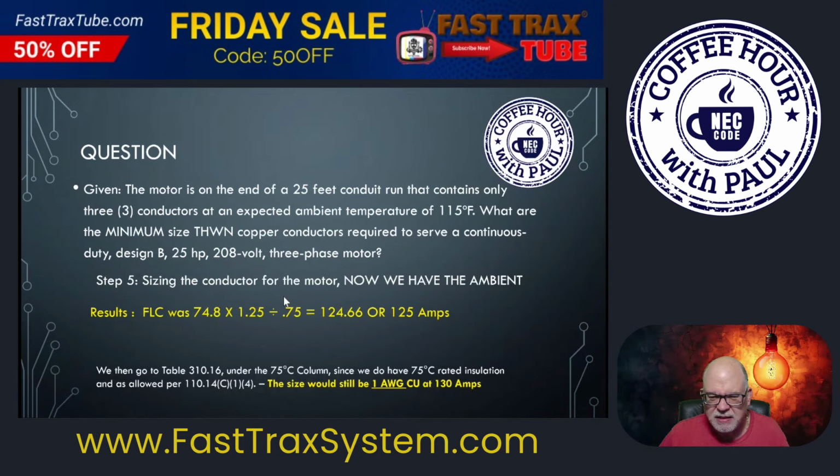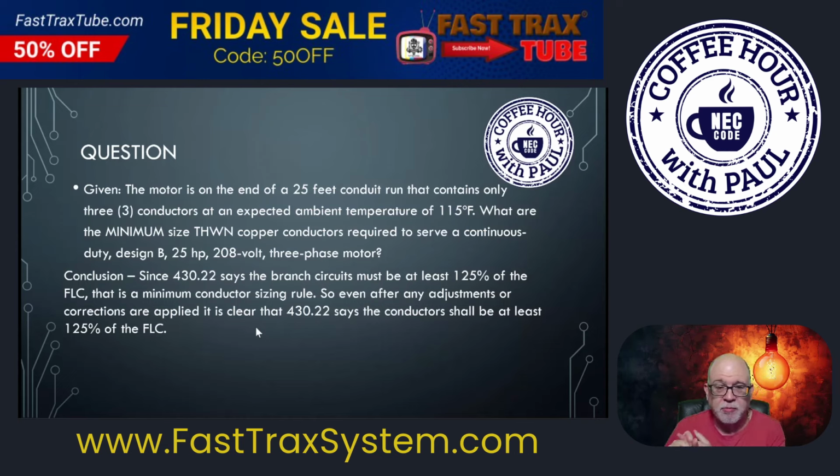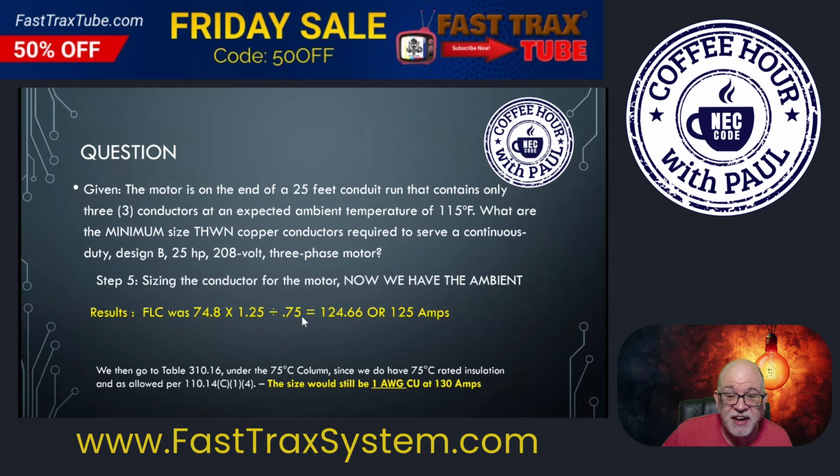So to answer that question, the conclusion: 430.22 says the branch circuit for this motor has to be at least 125% of the FLC, even after the adjustment or corrections. And by the way, people ask me this, so let me go back real quick. If I had a number of current-carrying conductors adjustment in this as well, it would have simply been 74.8 times 1.25 divided by 0.75 divided by whatever that adjustment would have been, whether it's 80%, 0.80, the same scenario.